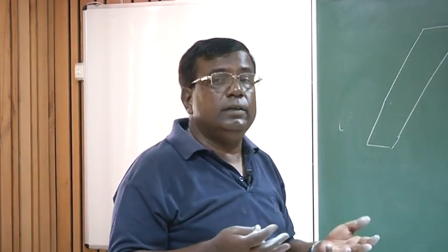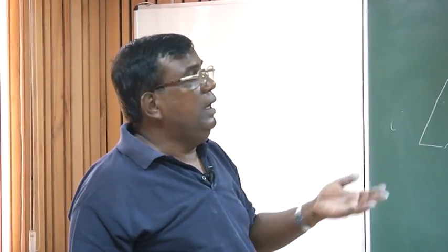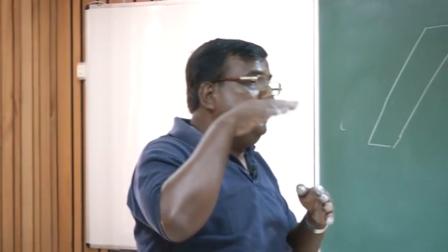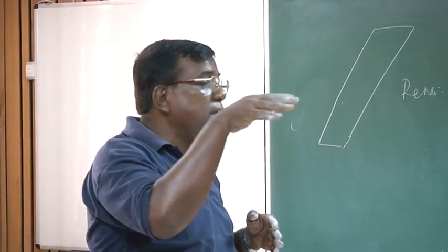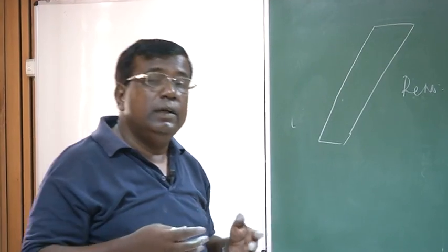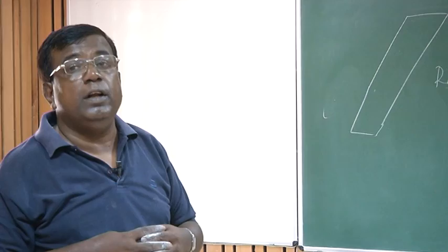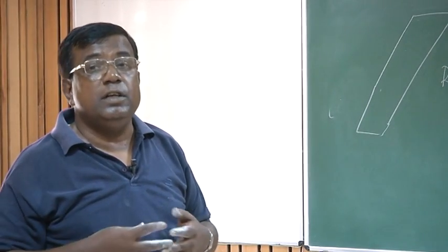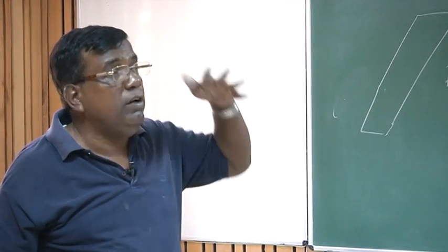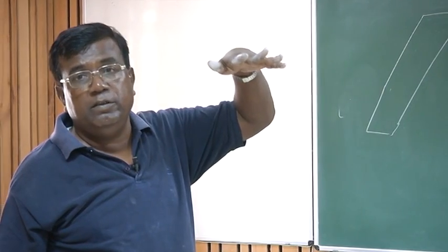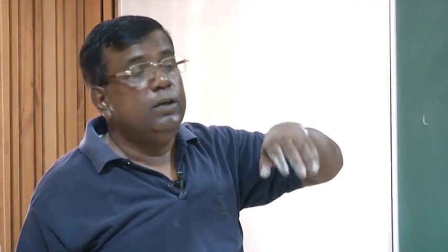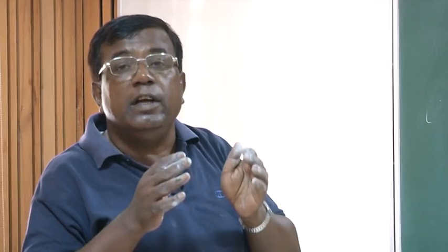So how much advantage it has given. Once I say I am ensuring that the flow in a tunnel has the same Reynolds number, I am actually talking about dynamic similarity. If I am testing for high speed, then I must ensure that the Mach number is the same. That is, whatever Mach number the actual airplane was experiencing, the same Mach number the small model in a tunnel should also experience.